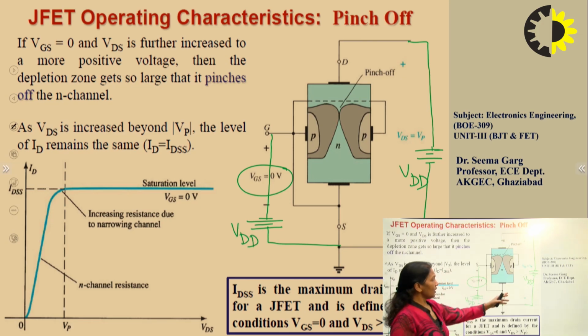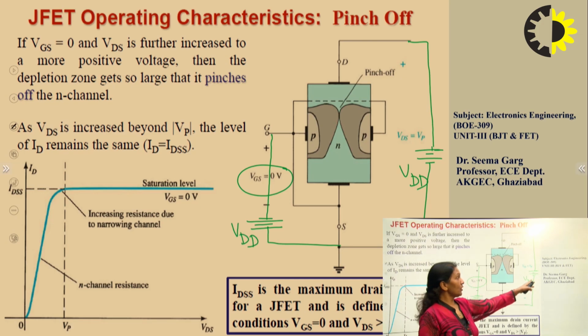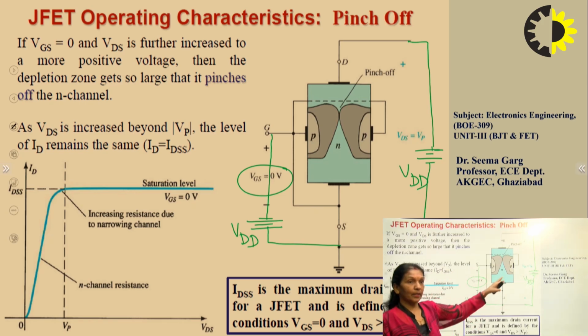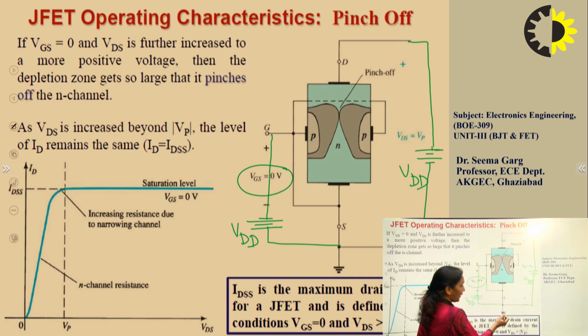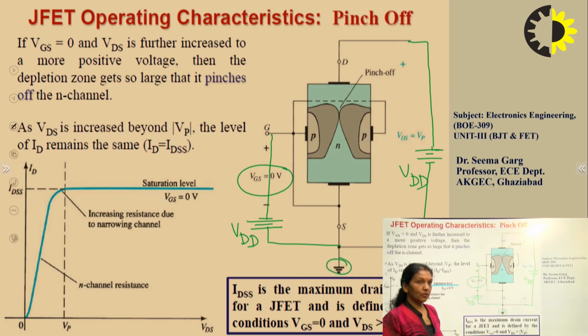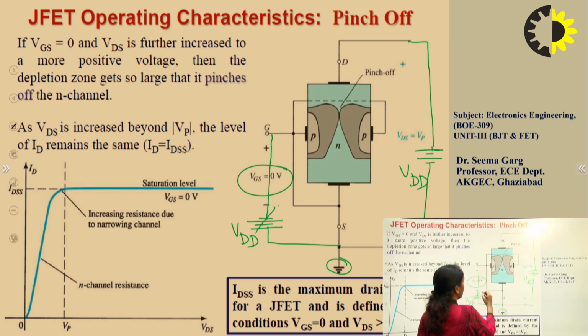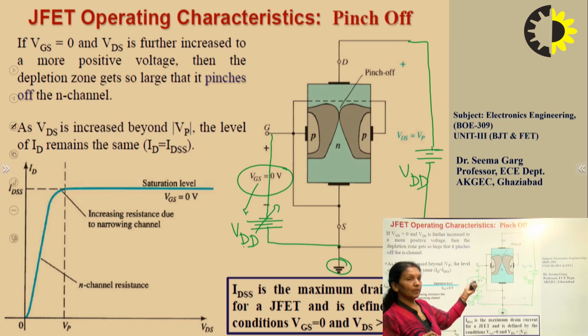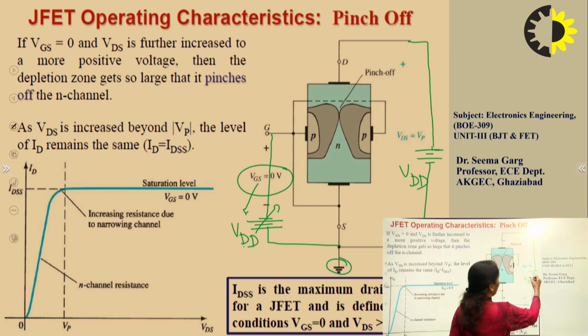So both the potentials are the same. One is at the positive potential, another at the negative potential, and because of that reason the source terminal will be at the ground potential, the 0 potential. So initially we are keeping VGS equal to 0. If we are keeping VGG 0, then obviously VGS will be at the 0 potential,